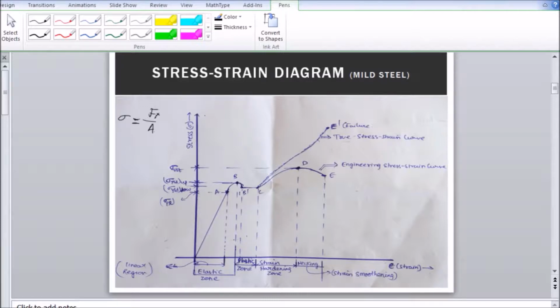This is the resistive force Fr, and this is the resisting area AR. So Fr over AR will be the stress. Now, when force is applied, for example a tensile force, that means there is a certain specimen and we are pulling it. This is a tensile load, which we already discussed in types of loads. When pulling action is there, the specimen elongates and its length increases by some amount.